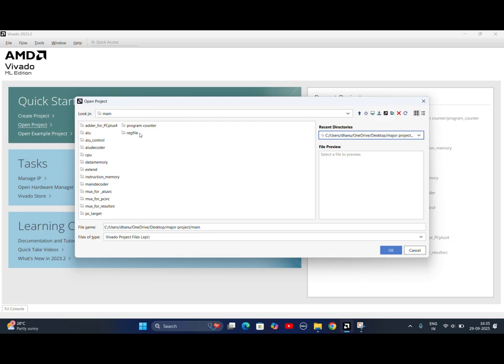After elaborating we have synthesized the design. After this the entire block will be instantiated in the same file for the CPU, and after writing the test bench and giving the input, we will get some output. So this gives the synthesized single cycle RISC-V architecture.